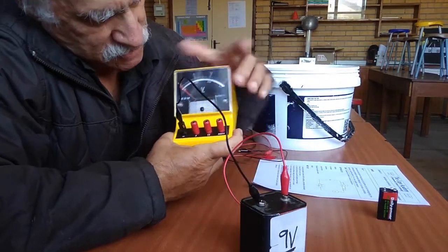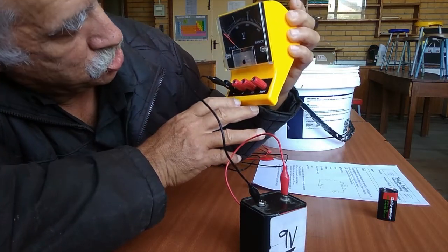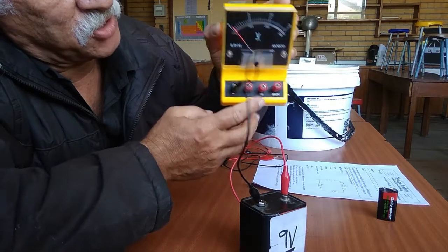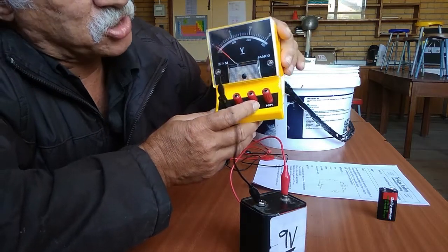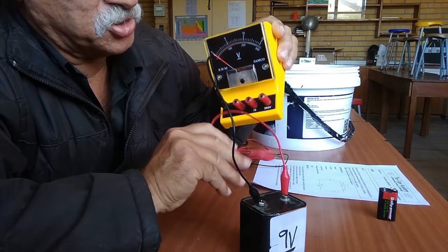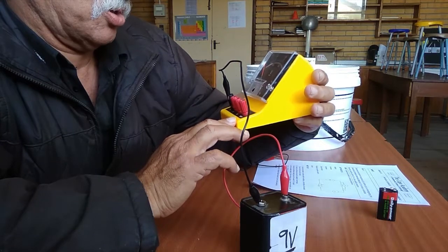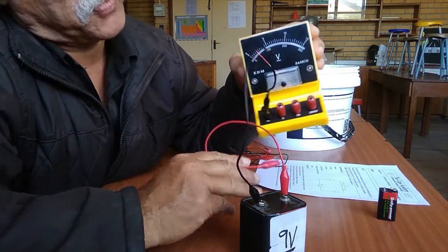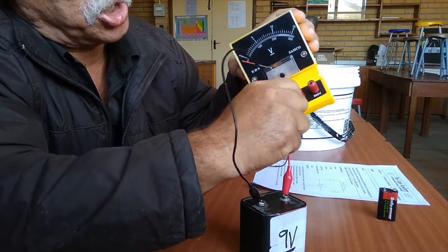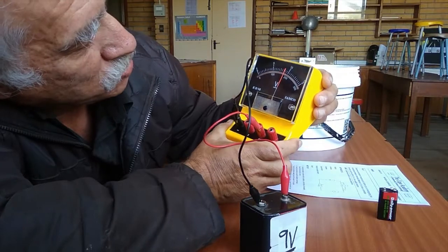So now this is a 9-volt battery, and it says minus, 3. We attach that to the 3. We're going to send this voltmeter into paroxysms. The little needle is going to go right past the end. So we're going to go for 15, and it can also do 300 volts DC. It's a DC meter, and we've got a DC voltage. So let's put it on the 15, and let's see what it reads.